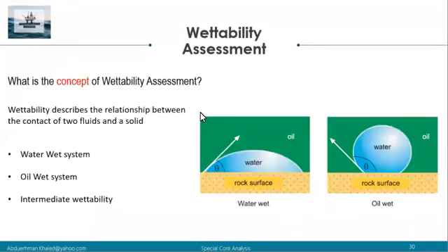And now we go to, actually for me, the most important aspect in the reservoir, which is the wettability assessment. So what is the concept of wettability? Maybe some of you are wondering why I put wettability last, because many authors put wettability at the very beginning, because wettability contributes to relative permeability and also to capillary pressure. But for me, I wanted to put wettability at the end of this presentation, because once you understand the concept of both relative permeability and Pc approaches, now you can have an idea about the effect of wettability on these two things.